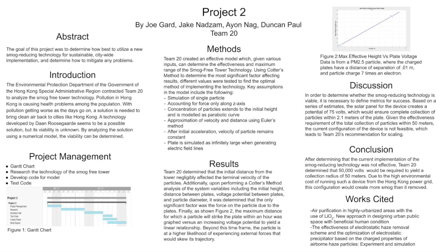Notably, while we originally modeled the force due to the device on the particle via a calculation involving the charge density of a plate, this proved to be inaccurate as the exact charge density of a given plate was unable to be determined. Due to the challenge of manipulating the charge density of the plate, the team made the decision to switch to defining the electric field strength as a function of voltage and the distance between the plates of the device. This was far more intuitive than the first method of calculating the electric field force, and it allowed for easier analysis of the viability of the device when using values of voltage versus charge density.